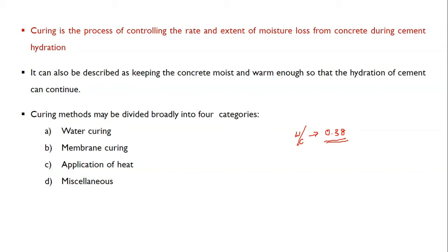Yes, the first thing is the environmental conditions. Maybe the season is summer, so the outside temperatures are very high. Therefore, the water that you have added to the concrete is lost due to the surrounding temperature. The second one is that the hydration process is an exothermic reaction. Heat is generated in the chemical reactions, and we call that heat the heat of hydration. Because of the heat of hydration, the member itself gets heated from the inside, so whatever water you have added is going to evaporate.